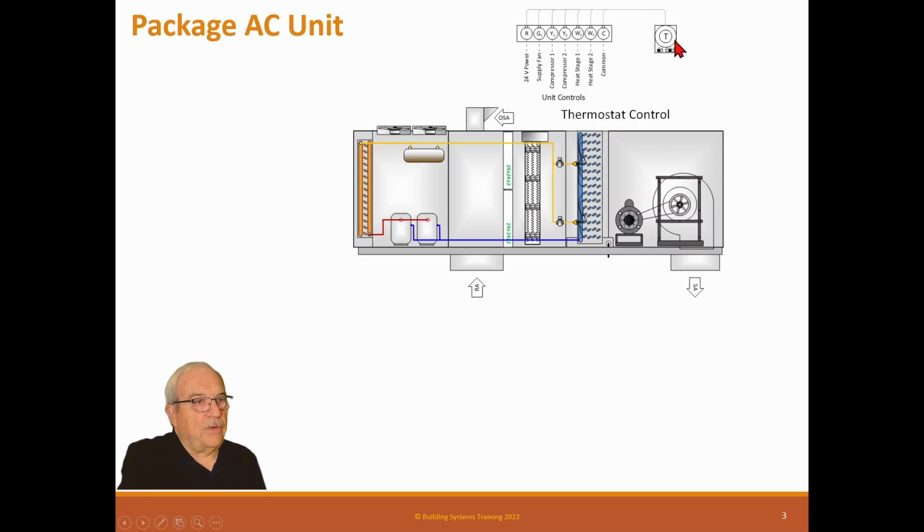The reason a regular thermostat, a thermostat that has either a bimetal unit in it or a mercury bulb in it, doesn't need a common is because all these are commons. It just makes the circuit back. But if you need to use power here, like for a display, or if it has a thermistor that has a computer component in it, then it'll need a common to run that thermostat, but not to run the unit. So this is a normal temperature control.